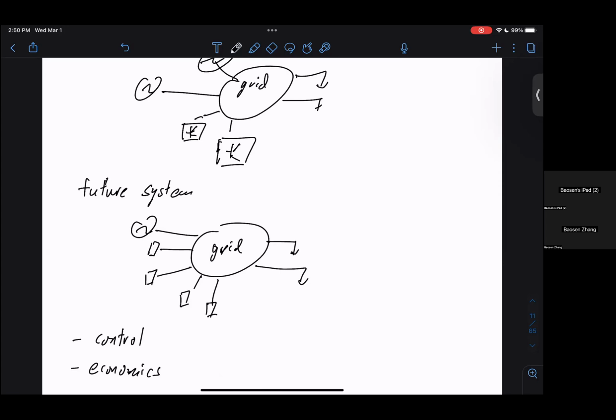You may not always be able to generate the peak capacity. So right now, what happens for a lot of solar and wind is you have a 10% band, so you only go up to 90% of your max production. You leave some wiggle room to do this kind of frequency response. Then you will want to get paid because you could have been generating more. Remember, for these kinds of resources, generating power is free to you. There's no fuel cost. You want to generate as much as possible, and you want to get paid for that.